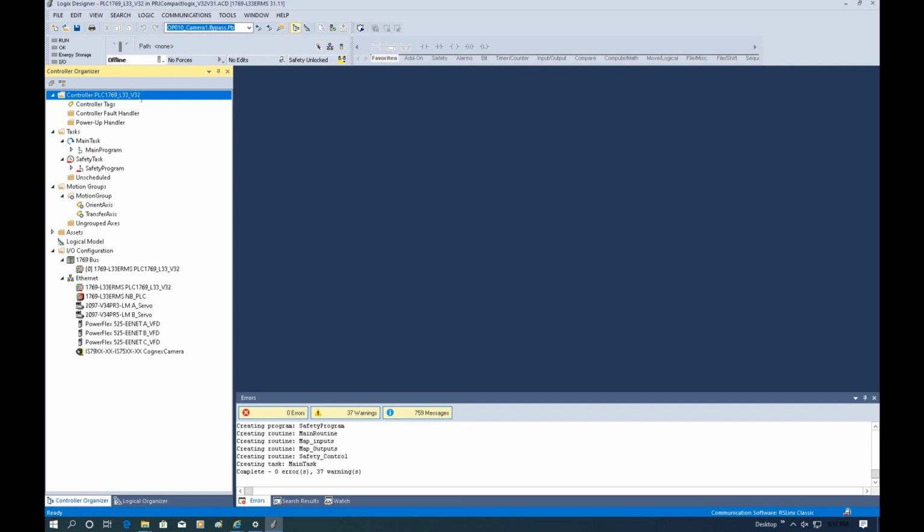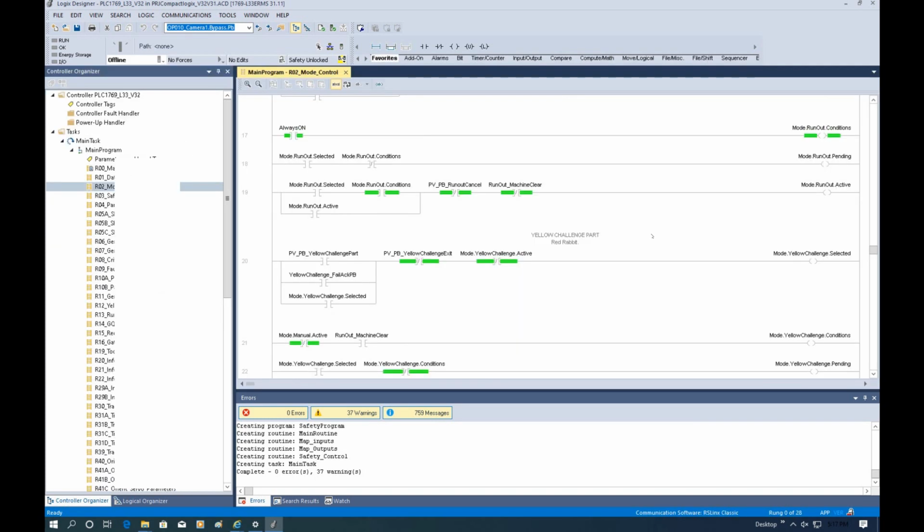So we can see that the name is still the version 32 name. That's fine, no problem. And everything is here. We can see the run now mode. So we can imagine if it is me using version 31, I can look at the offline program to check what conditions cannot be reached, and tell the on-site maintenance or operators to turn on something or reset something to troubleshoot the system.